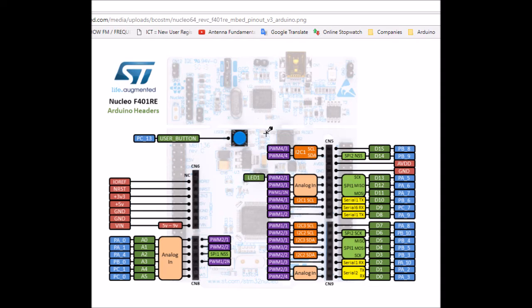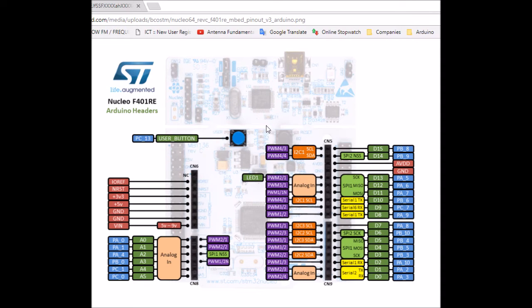With this mode, it's a good idea to use a timer trigger for the ADC so that the ADC doesn't go as fast as it can, which can cause a problem when using RTOS or kernel. And you also have to use DMA to transfer data to memory if you have multiple channels, because the ADC has only a single output data register, so you would use DMA to transfer data to memory automatically. If you didn't quite get what I mean when I talk about timer and DMA, don't worry much, I'll bring it up again when I get to CubeMX.